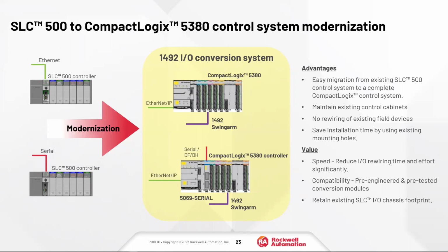And that serial module is designed to support Modbus. It's also designed to support migrations like this. So it is a good idea when you're doing SLC migrations to diligently look at all the communications that you have. Some of those communications you might be able to upgrade to Ethernet, like if you're communicating to a PanelView, and if you're using Data Highway or ControlNet or something, we can definitely help you migrate that to Ethernet.